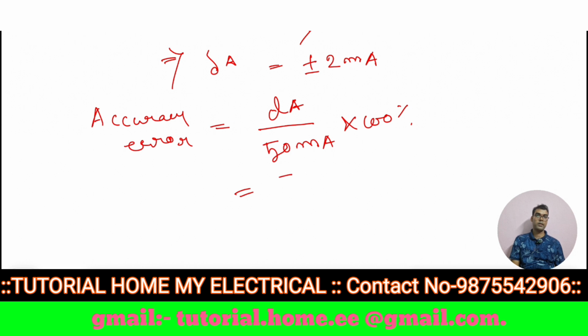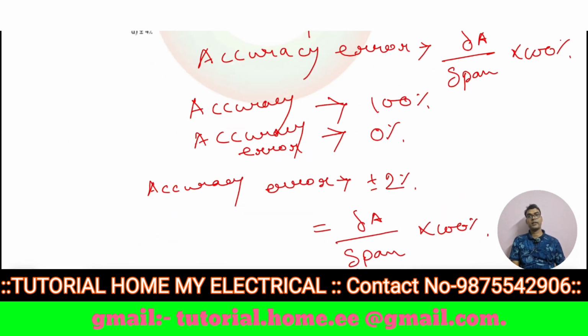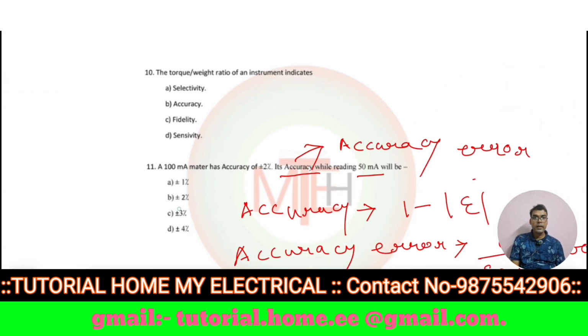Now d is plus minus 2 milliampere by 50 milliampere into 100%. So the milliampere cancelled, it is plus minus 4%. Okay, the answer is plus minus 4%. Option D is correct answer.